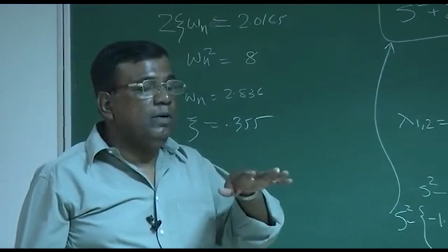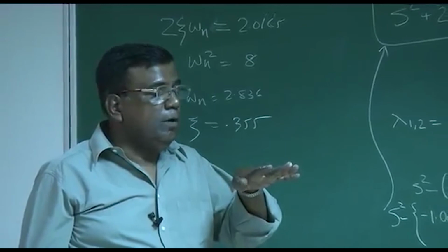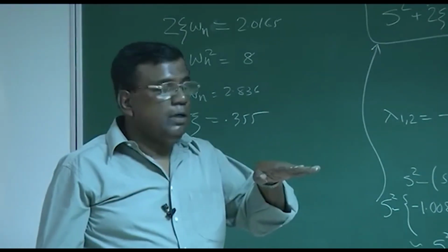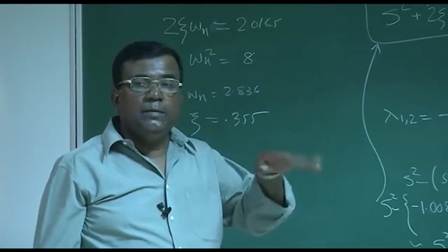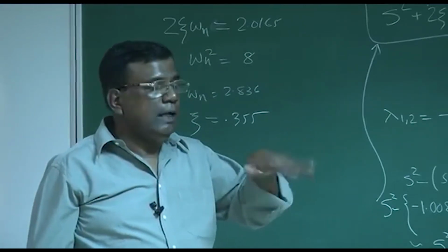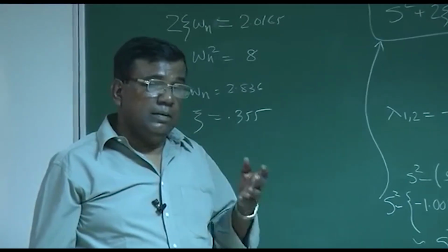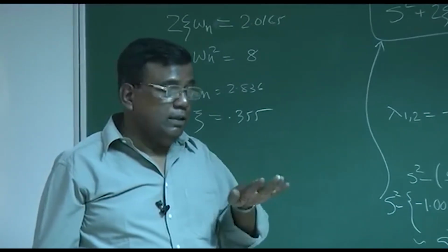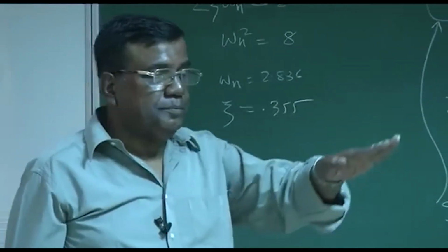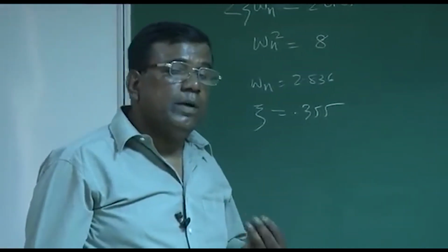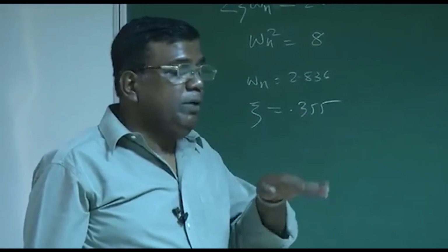The two predominant ways the aircraft can respond: one is short period type, that is, the disturbance immediately damps out, whose real negative root will be large, that will behave like this. And the roots where the real part is negative, but not that large, that is something like this. So typically for an aircraft, longitudinal characteristics are dominated by two modes. One is the short period mode.